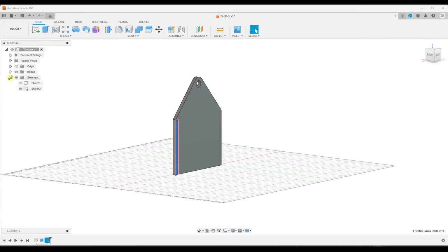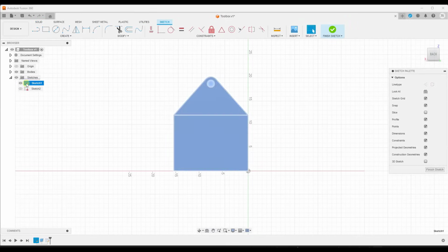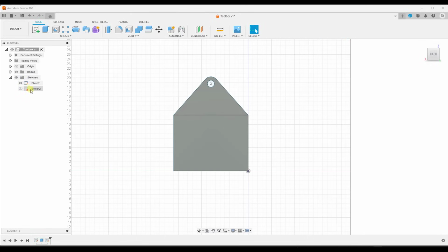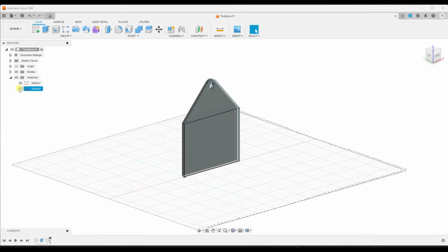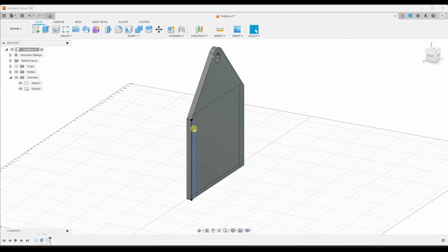And you can see your different sketches, by the way, over here in the Sketches window, right? So you can like toggle these on and off if you want to see them or not see them in the space. You can also come back in here and edit those sketches just by clicking on them, right? So we don't necessarily want to do that right now. We've got our sketches created. What we want to do, and I'm going to click on the little eye so that I can see this again, we want to take this sketch and extrude it into 3D.